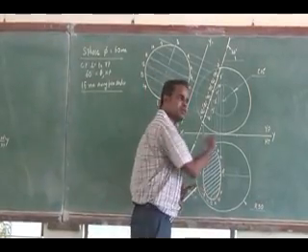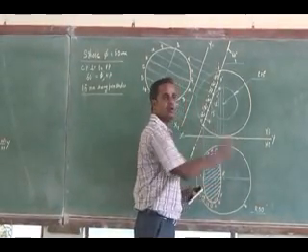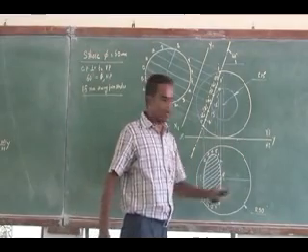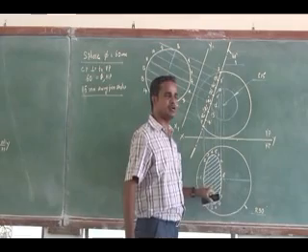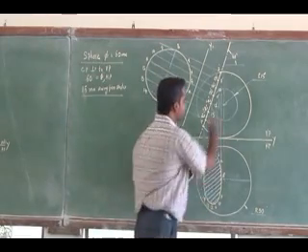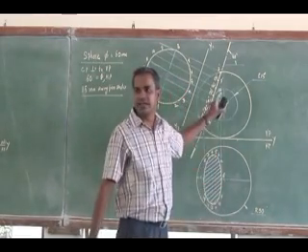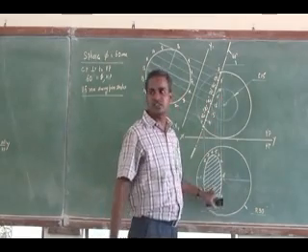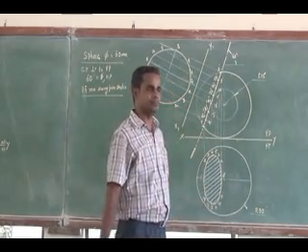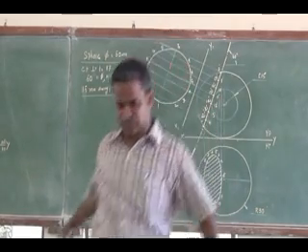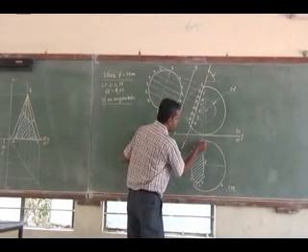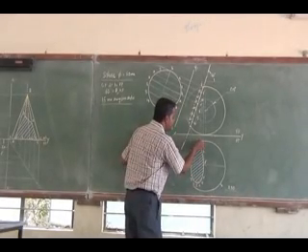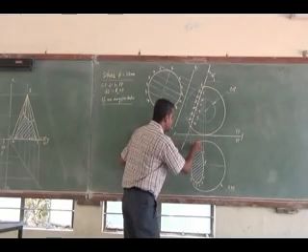Okay, first of all with a 2H pencil you connect it. Then you get a smooth curve. Then you darken it. Then you match the apparent shape of the section in your top view. Right? Then the retained portion, finally, the retained sphere and the retained sectional top view, you darken it. Right? Listen, I have to connect it with this. Tangentially, you have to connect it.